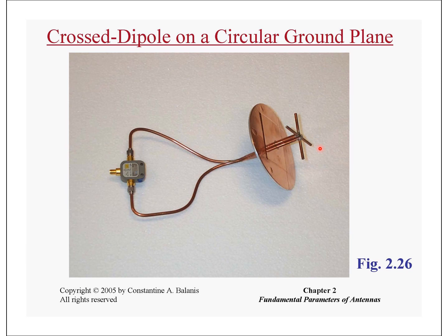The second condition for achieving circular polarization is that the phase difference between the x and the y component should be 90 degrees. That is achieved by this phase shifter. The phase shifter is connected at the input of the antenna. So this phase shifter will introduce a phase delay of 90 degrees or a phase advance of 90 degrees in order to achieve left hand or right hand circularly polarized waves from the antenna.